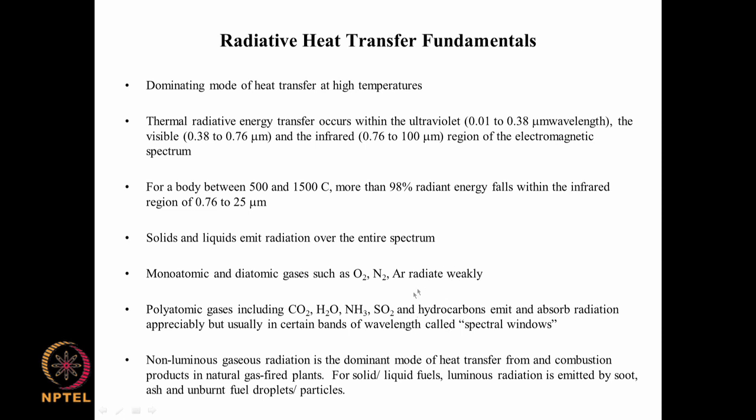And whether the role of these gases in the radiative heat transfer is significant depends on the temperature, and whether there is a significant amount of radiation in which these bands, the spectral windows of these gases, are important. Okay. So, non-luminous gaseous radiation is the dominant mode of heat transfer,